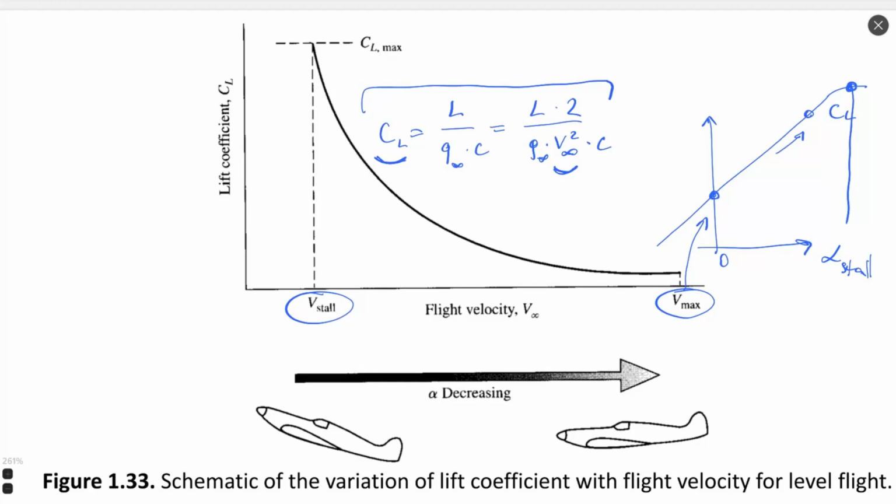Higher angle of attack, smaller velocity. It is not possible to keep the velocity as high as we had it at 0 angle of attack, just looking at this equation. And not just because we don't want to, but because we can't. Our engine energy is limited, so we cannot produce very high thrust to keep high velocity at high angle of attack.